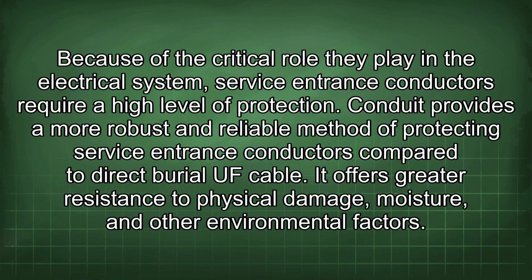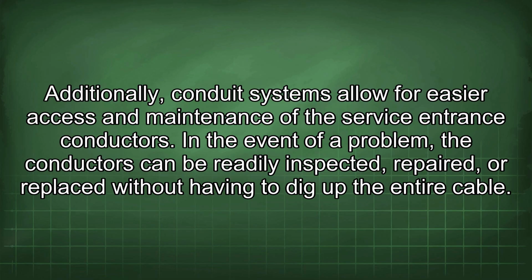Conduit provides a more robust and reliable method of protecting service entrance conductors compared to direct burial UF cable. It offers greater resistance to physical damage, moisture, and other environmental factors. Additionally, conduit systems allow for easier access and maintenance of the service entrance conductors. In the event of a problem, the conductors can be readily inspected, repaired, or replaced without having to dig up the entire cable.